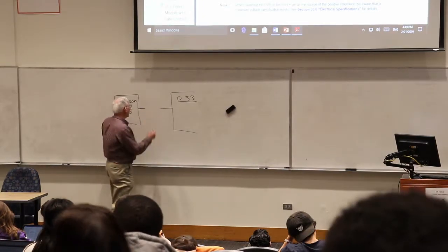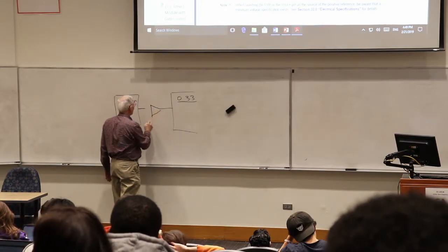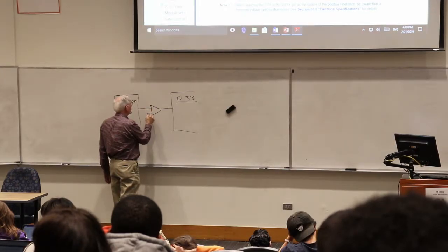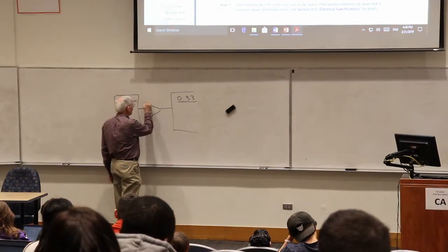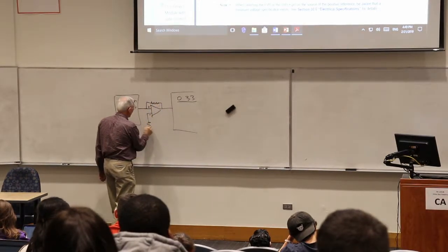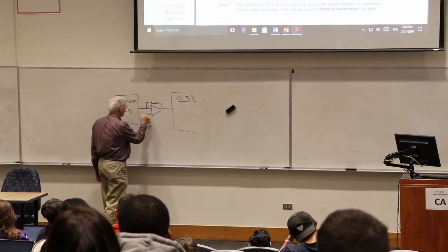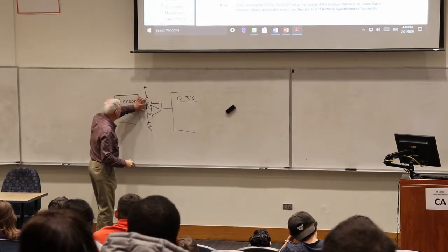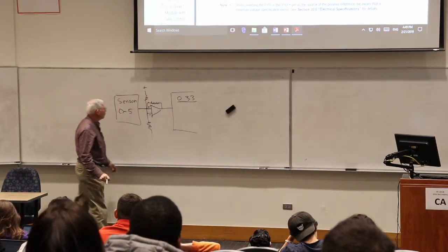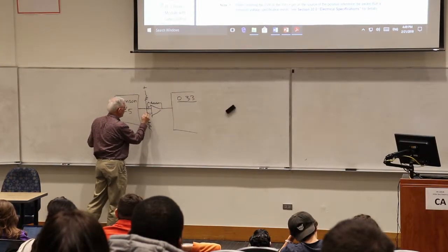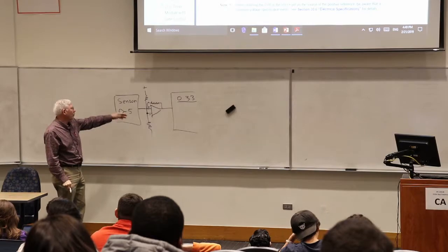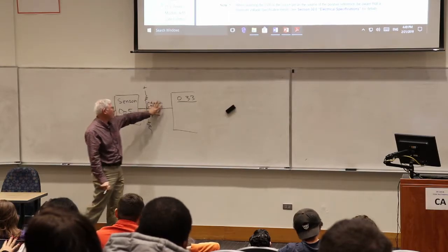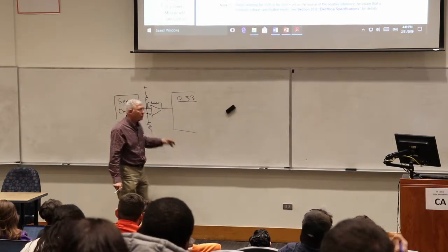So what we do is we put an op amp in here. And typically, we have it set up so that we give a little bit of feedback, and this defines the gain. And then we have a little bit of a voltage divider here, and this defines the offset. And so we pick these resistances so that we get this op amp to condition this signal to put it in exactly the range we want, to be 0 to 3.3 with the proper offset.